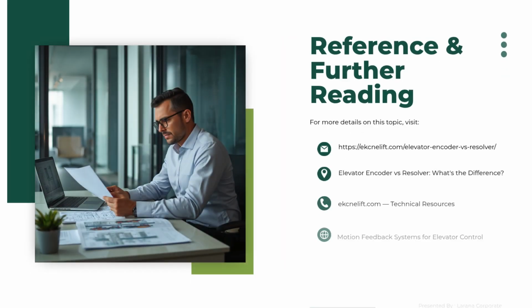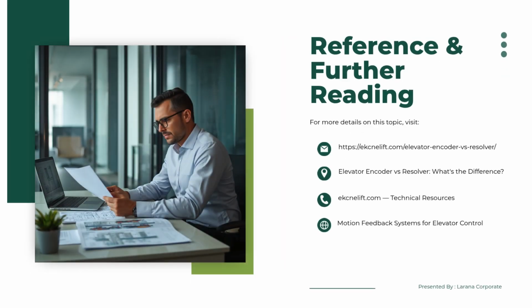Conclusion. So what is the difference between an elevator encoder and a resolver? Both provide motion feedback, but an encoder provides digital feedback that integrates more naturally with modern VVVF systems, PM motors, digital controllers, and high-precision passenger elevator applications. A resolver provides analog feedback and usually requires conversion hardware, but it offers strong durability in harsh environments with vibration, contamination, and temperature fluctuation. The better choice depends on the project.